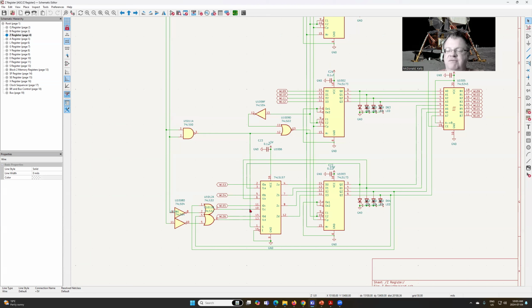And then we want to write 15 or 16 in. We've added these OR gates here because if 15 is a 1 and we get another one, we don't want to change it, and likewise for the 16. So we only want to change bit 15 or bit 16 if their respective control pulse is asserted.